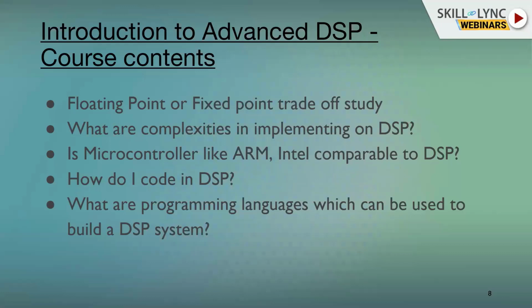So if we use the same Intel to compute a DSP algorithm, that's going to take a huge amount of toll, because it's going to use a CISC architecture, and it's not going to exploit the parallelism when compared to the DSP. Okay, how about ARM in this case? For example, if we have a 4-core ARM or an 8-core ARM, can we compare to DSP?